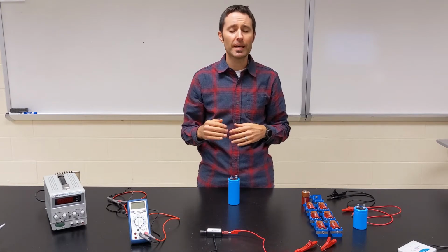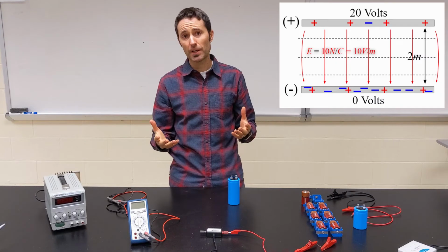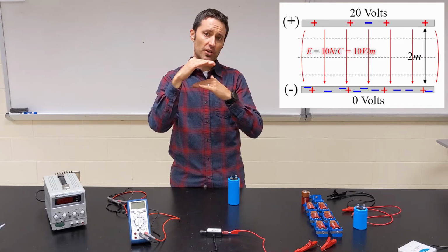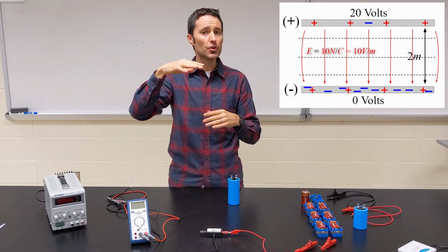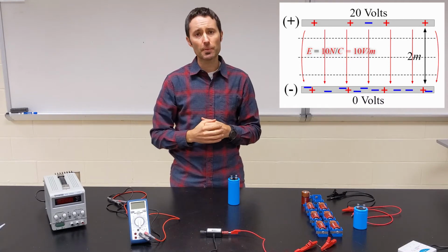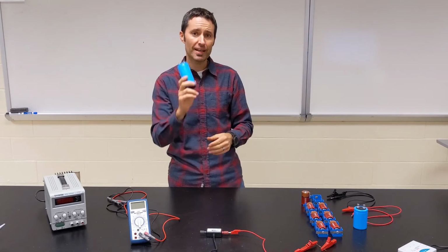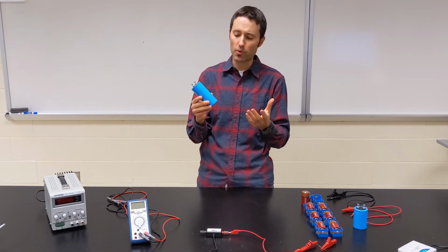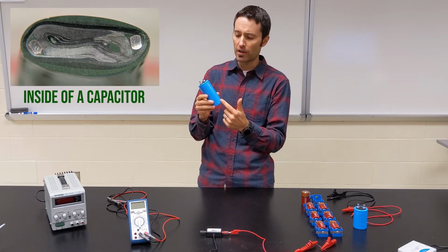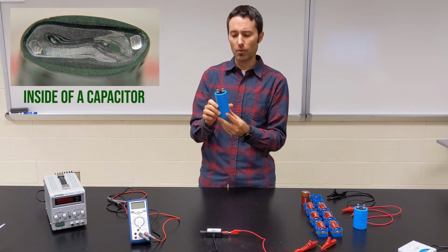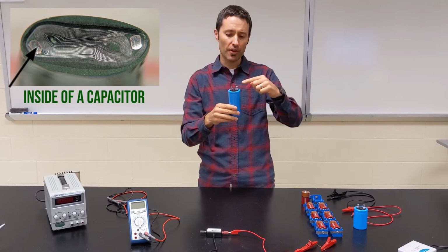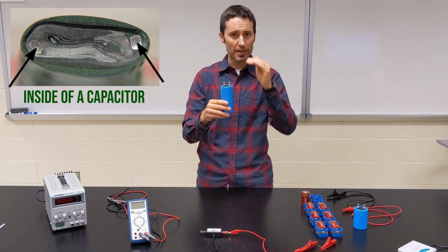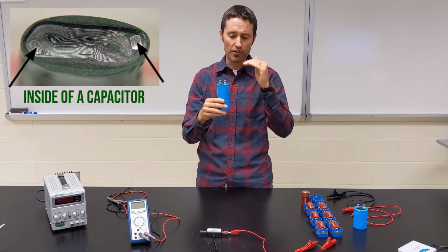insulated material. And in the context that we've talked about them, we know that two parallel plates, when there's a positive and negative charge on one and the other, there's a uniform electric field set up in between there. Well, this thing is a capacitor, and it might not look like two parallel plates, either neutral or charged, but inside of here are two pieces of metal, one connected to this terminal, the other one connected to this terminal, and they're separated by a very small distance by an insulator, so it doesn't allow the charges to go.